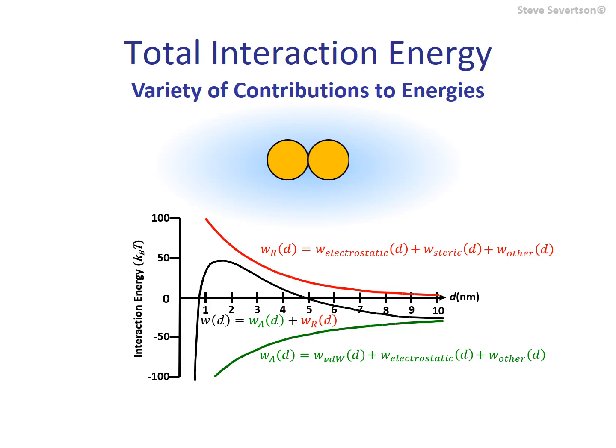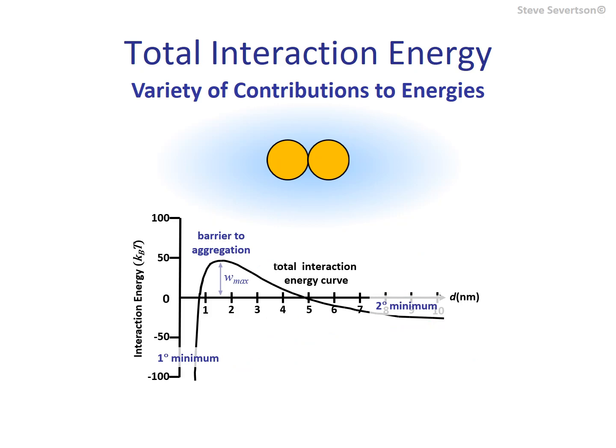Finally, it should be emphasized that for hydrophobic colloids, stability refers to kinetic stability. Such systems are always undergoing destabilization, and stability is a measure of the rate of destabilization relative to a given time frame. The maximum in the interaction energy provides the energy barrier to primary aggregation. This is an irreversible process. Although secondary aggregation is possible at greater separation distances, these interactions tend to be quite weak, providing flocs that are readily redispersed.